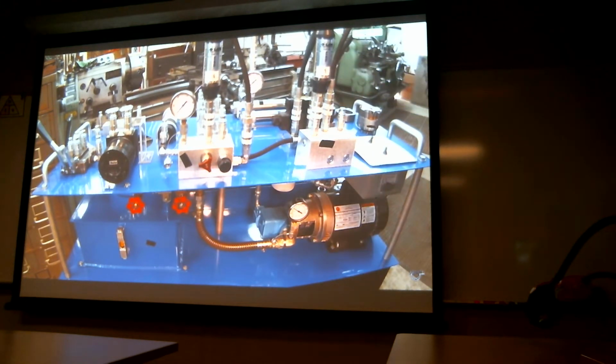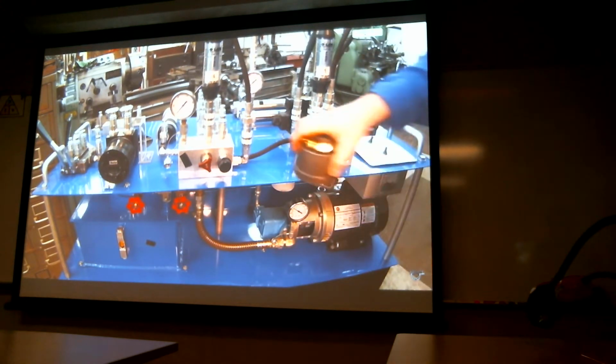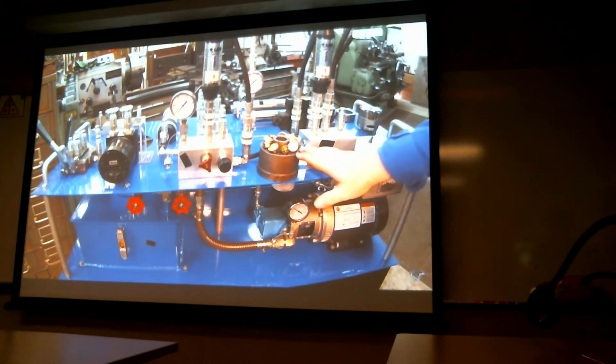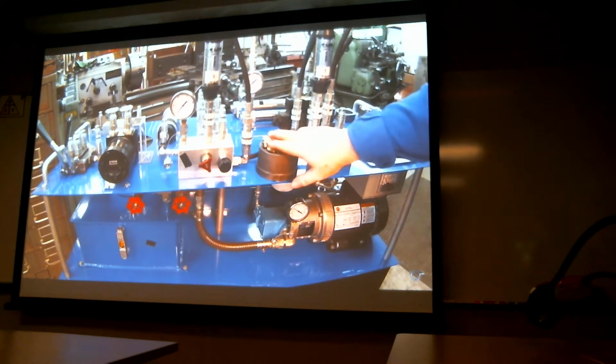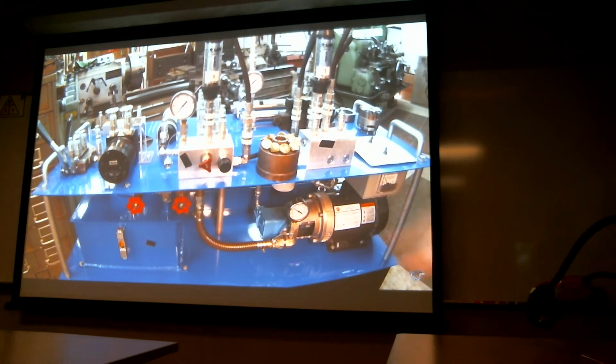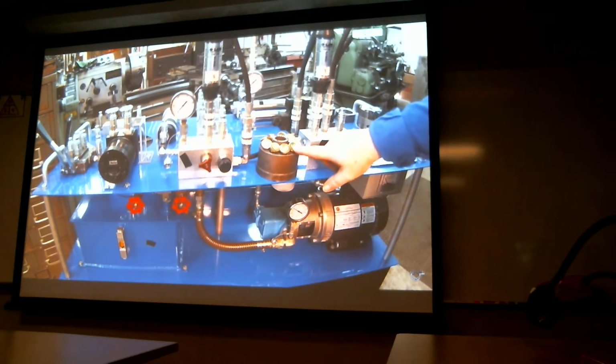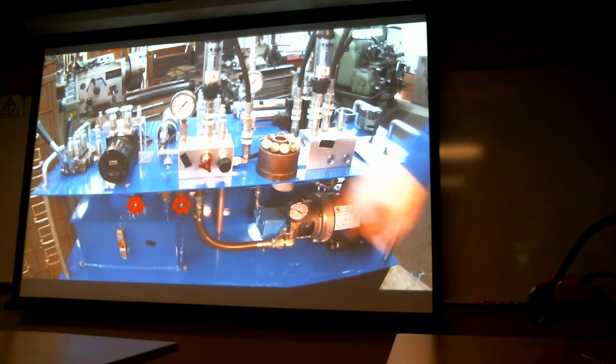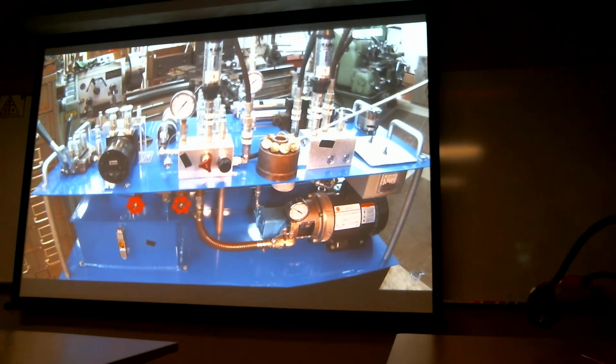All right, on a piston pump, this is called your rotating group, and you see your nice little pretty shoes right there, your little brass shoes that spin around on the inside of your pump. I know it's hard to see, but right there in the middle of this piston is how it gets lubricated, okay?